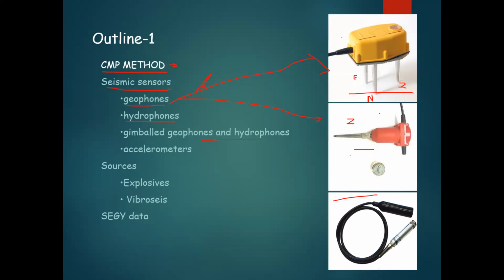So I was talking about how for an undulated surface, we need to have independent geophones so that the geometry of data acquisition remains even. If I want to plant a geophone on an undulated surface at every 2 meters or 5 meters or 50 meters, I can do that easily. But here, what will happen? The land is uneven, so I'll have to apply a static correction and a correction due to the elevation. We'll be talking about these corrections when we talk about seismic data processing.